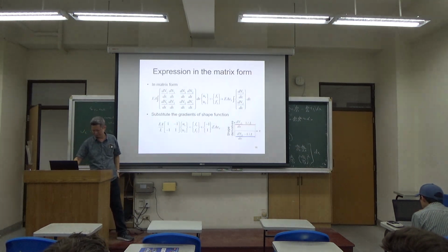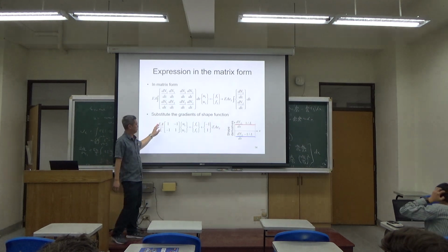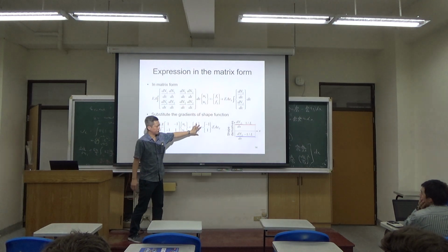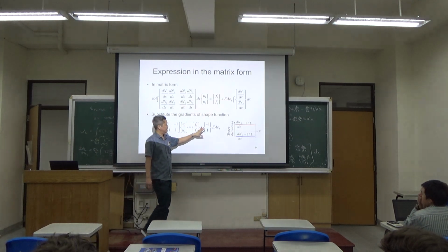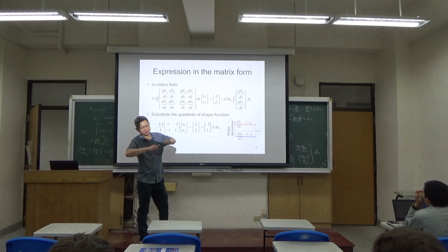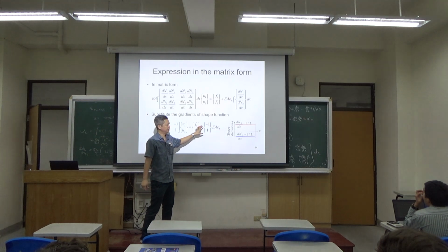Okay? So how do we read this? Now, the first two terms is still the Hooke's law, but the introduction of the thermal expansion is effectively like stretching a rod by extra thermally induced force. Okay?